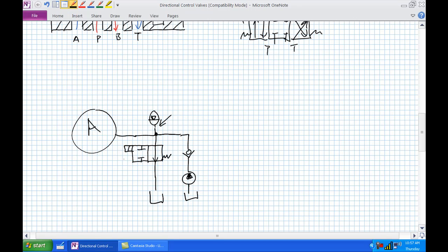What this is implying here, this is a normally open valve. So that means basically solenoid A needs to be energized at all times to close it. Okay? So basically, normal system operation, the pump, what's that check valve doing? It's allowing fluid flow this direction, preventing a bleed back through the pump here.